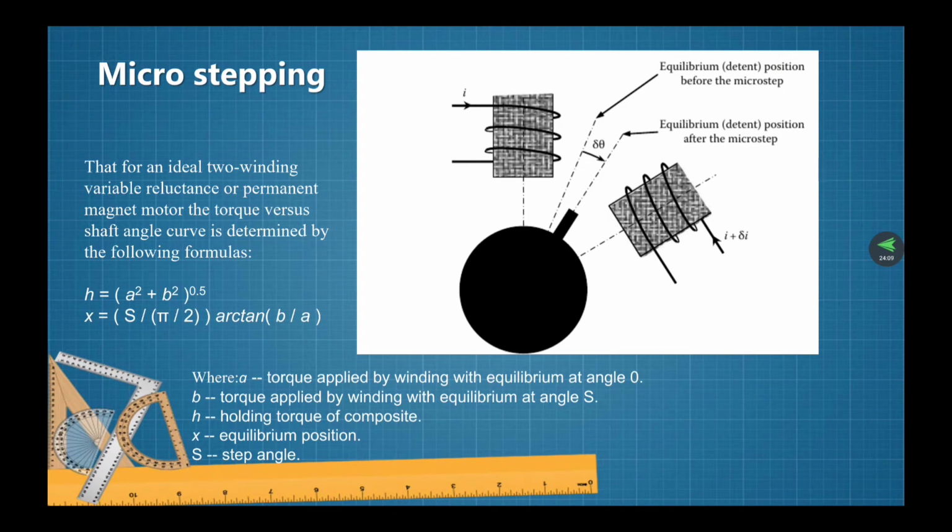We have seen how full stepping and half stepping can be achieved simply by using an appropriate switching scheme. Half stepping occurs when phase switching alternates between one phase on and two phase on states. Full stepping occurs when either one phase on switching or two phase on switching is used exclusively for every step.